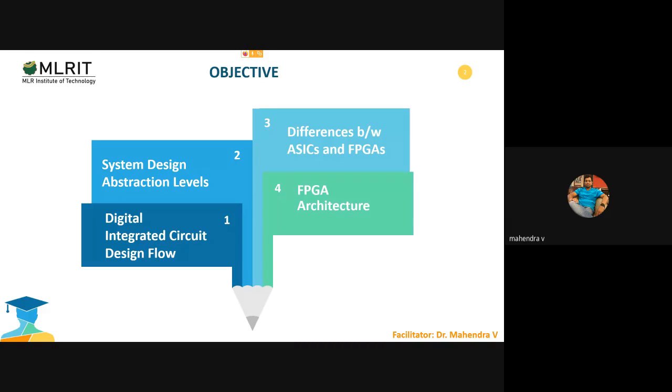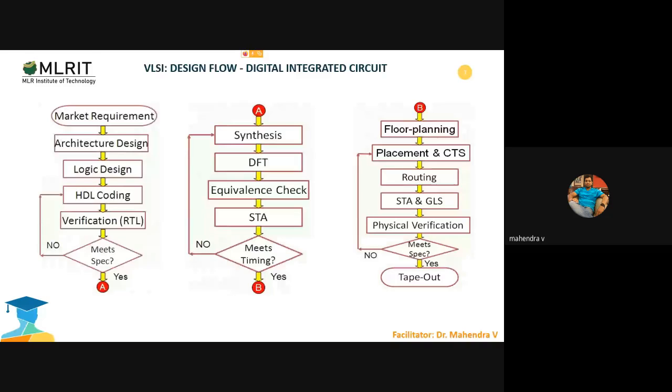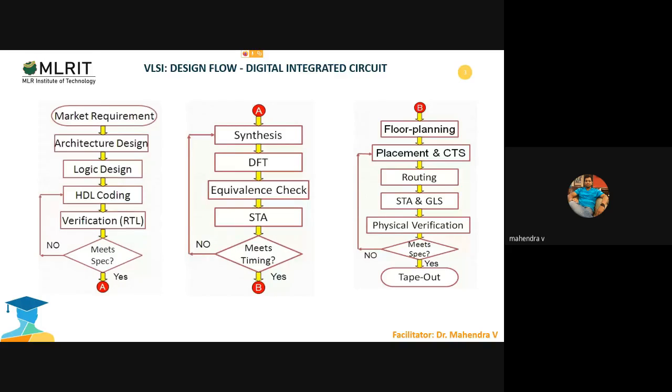Now, just have the basic concepts. First, we will see what is the integrated circuit design flow we follow. This is the digital integrated circuit flow, or simply the VLSI design flow, which can be used for designing digital integrated circuits using field programmable gate arrays and also ASIC. In my previous webinar, I gave you the concept of full custom design, semi-custom design, and field programmable gate array design. The flow I am projecting here will help us go through the semi-custom and field programmable gate array.